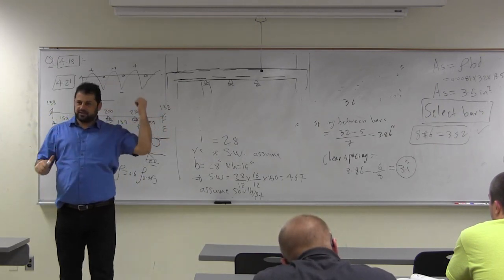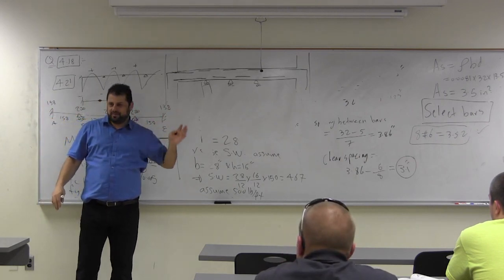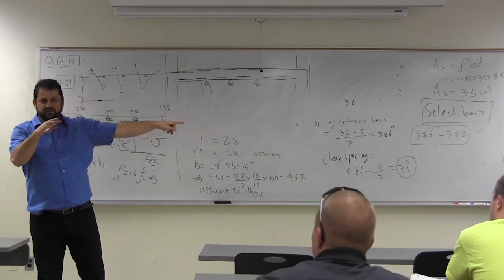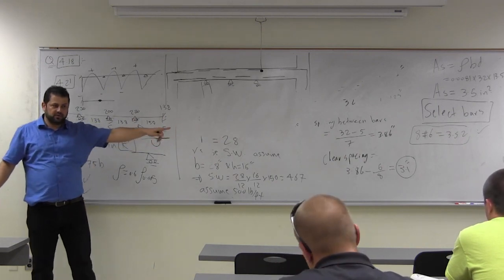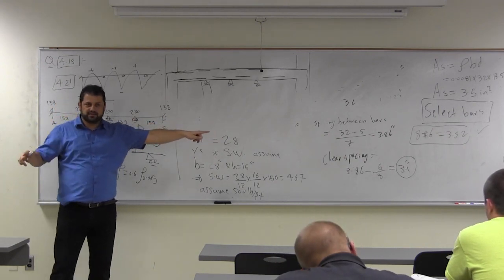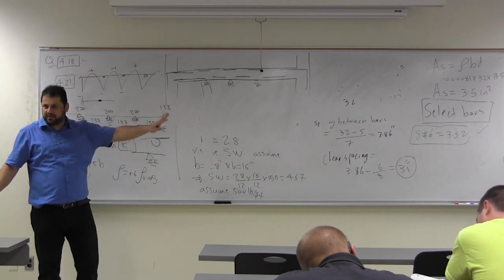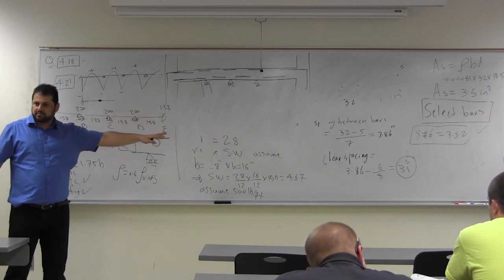By the way, in the previous question, the last thing I need you guys to check is to check rho minimum. Check whether rho, the one that we use, 0.6 rho, 0.005, must be greater than rho minimum. We know it's less than rho max because rho 0.005 is less than rho max, which is for sure it will be more than rho minimum. But to complete that question, you must check rho against rho minimum.